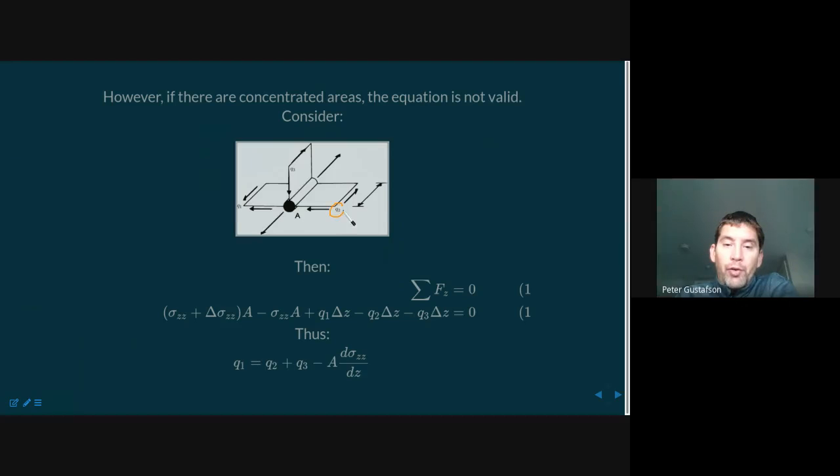This Q2 really applies for here and here. And again, remember what we do with shear. The magnitude is the same on the two sides of the corner, and the arrows point either towards each other or away from each other, depending on where you are. So here, Q2, they're both pointing away.